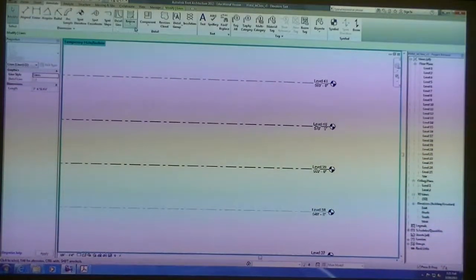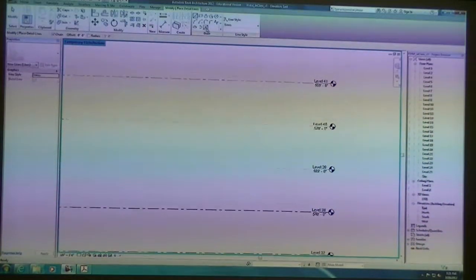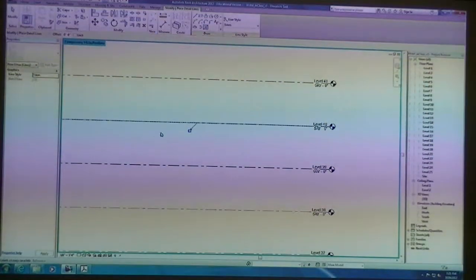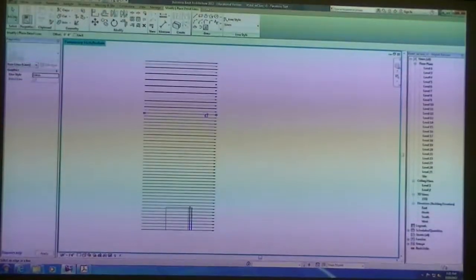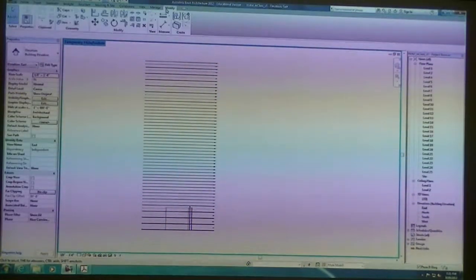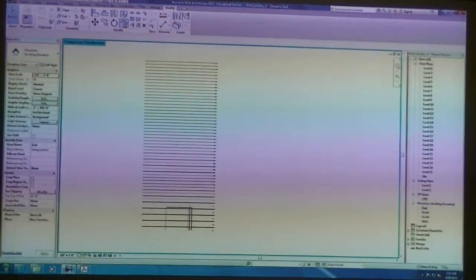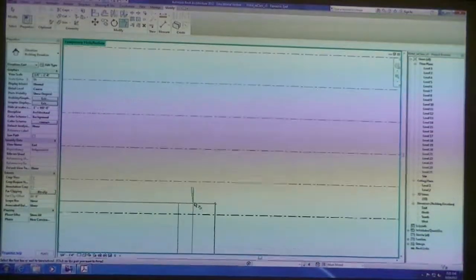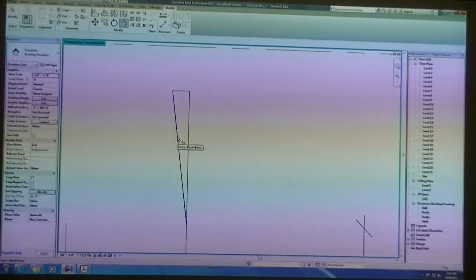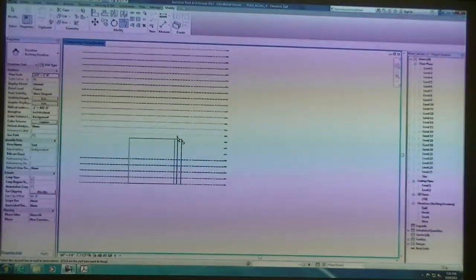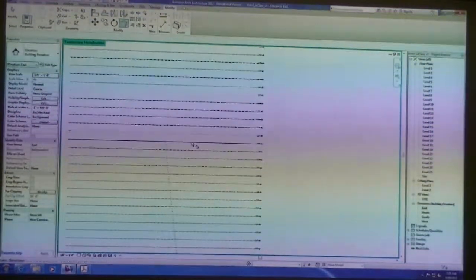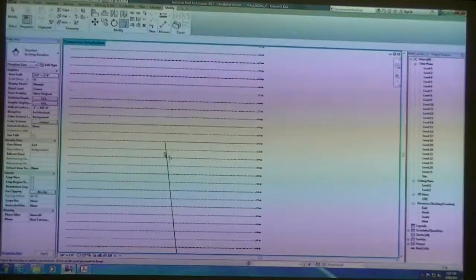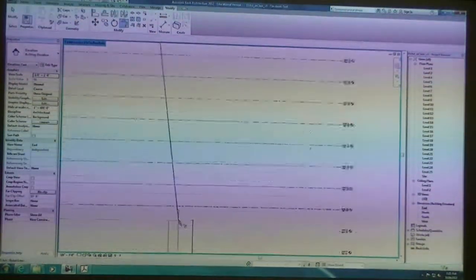And I will draw another annotation line by clicking on this datum at level 40. What this allows me to do is trim and extend this angle. So I'm zooming back in on the angle, and then I'm coming up to my annotation line and using trim and extend.